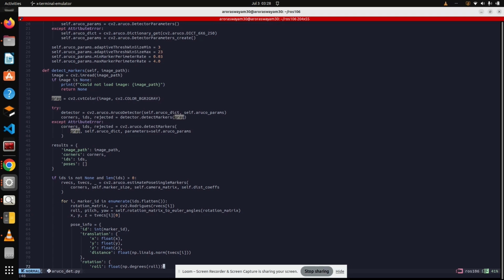So currently what we have done is we identified the ArUco markers and got their IDs, and now we will be identifying their poses. We know this is the identity of the robot. Now we need the pose, to know where the robot is. This pose identification is again done using a built-in function, the estimatePoseSingleMarkers function, as you can see here. I supply the desired parameters and I get the rotation vector and translation vector.